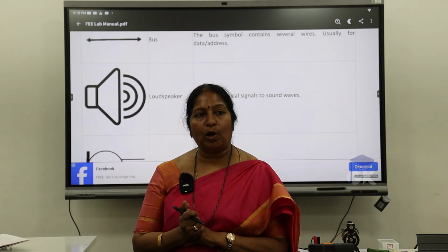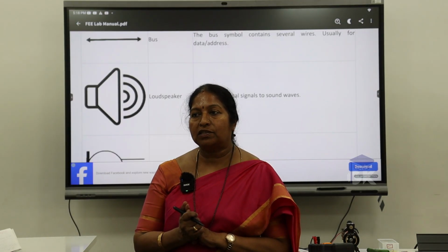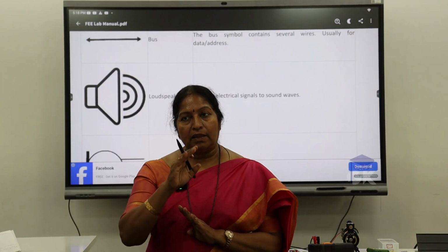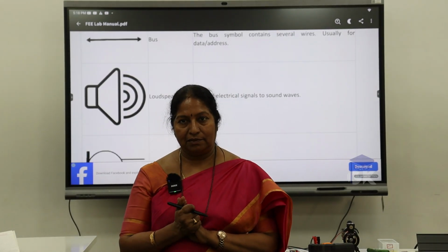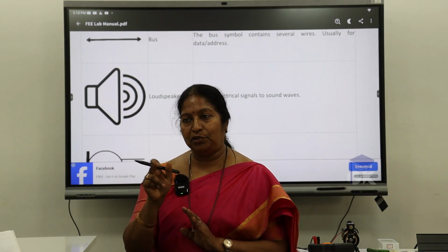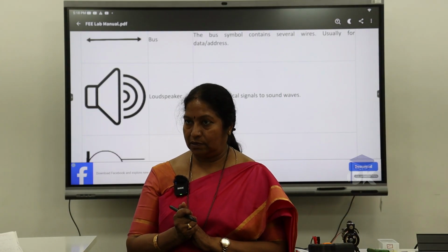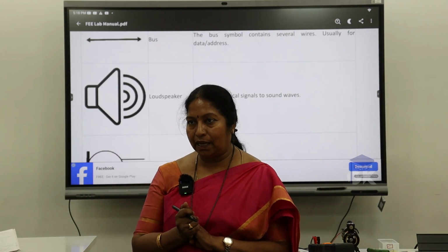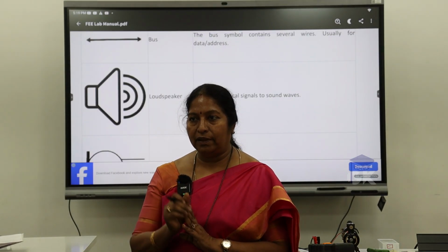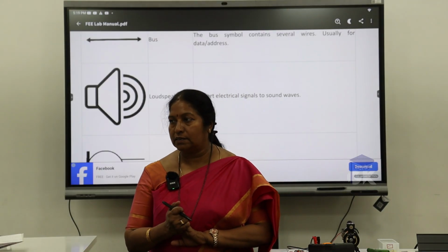I just explained in the morning itself. What is the amount or the capacity of current bearing of that wire? Once again, the wire will have some resistance. Correct? The wire which has been connected inside the fuse, from one terminal to the other, will have a resistance. How do you calculate the resistance? Once again, rho L by A. Area of cross section, length of the wire, what is the material used? Based on that, you can calculate the resistance.